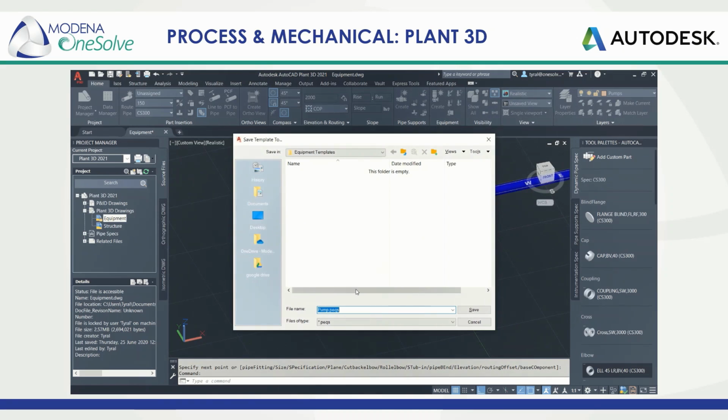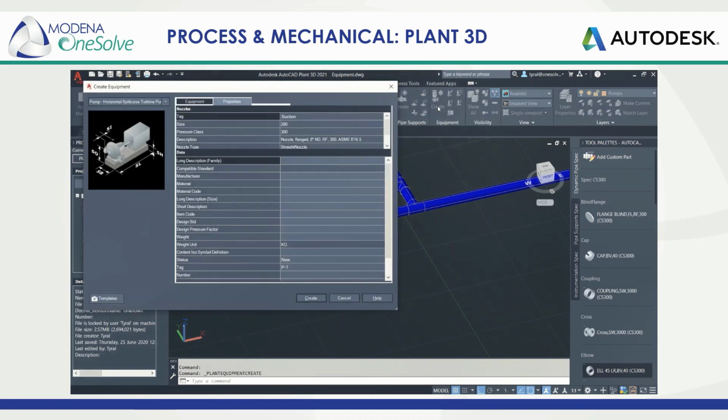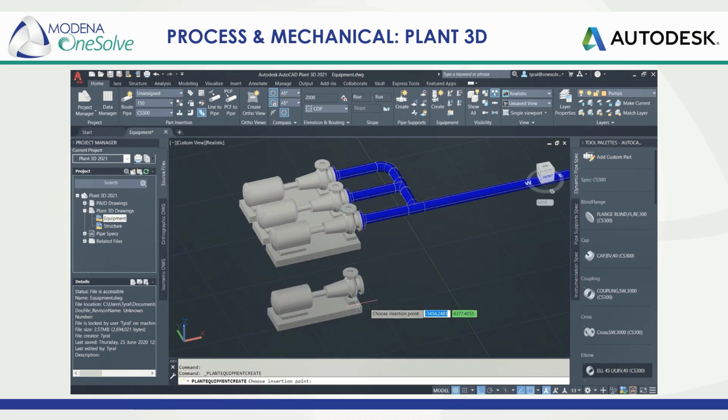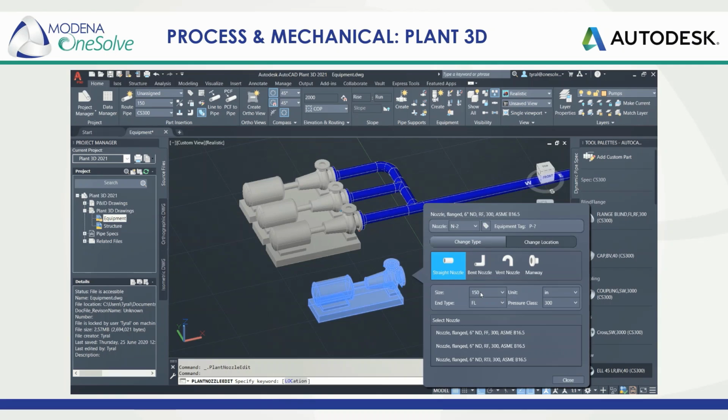You can, at this stage, export this piece of equipment out as a Plant 3D piece of equipment, and this allows us to leverage this configured model in the current or in new projects. Once saved out as an equipment template, very straightforward to bring that back in. It's a matter of creating a piece of equipment based on the template, and there you see how the data has come back through and how the nozzle information has already been defined.